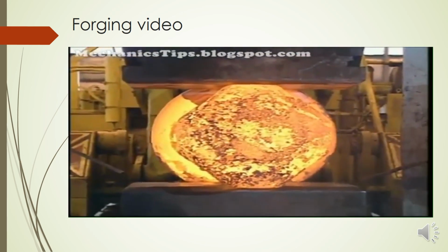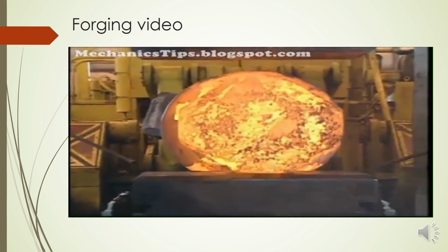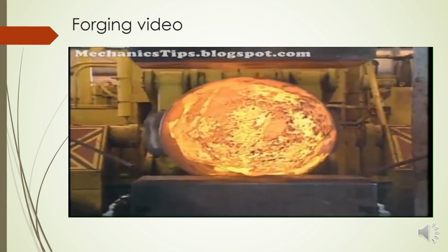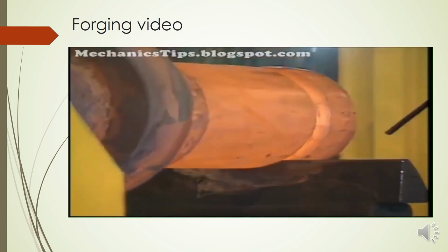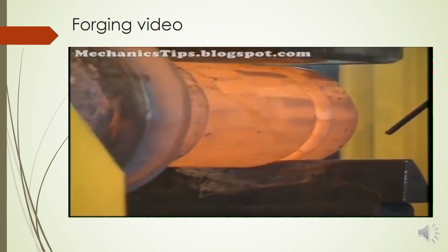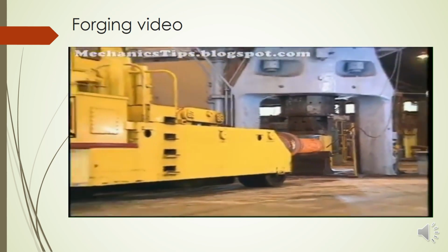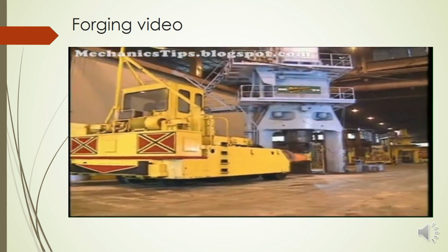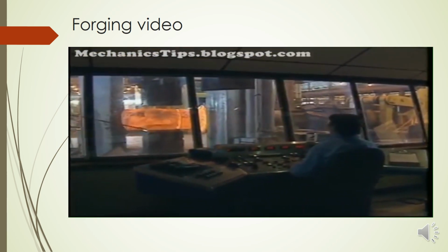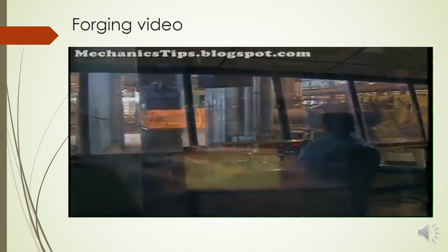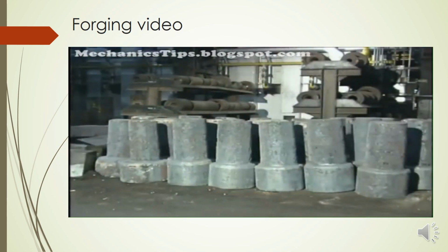Lengthening and upsetting are typically done using multiple impacts, as the workpiece is incrementally advanced lengthwise and rotated about its longitudinal axis. There is essentially no limit to the size of forgings that can be made using open die forging. They can range from a few centimeters to 30 meters in length and weigh from a few to up to several 100,000 kilograms. Although fairly complex shapes can be made using open die forging, most are rather simple solids or hollows requiring considerable machining to achieve final shape.